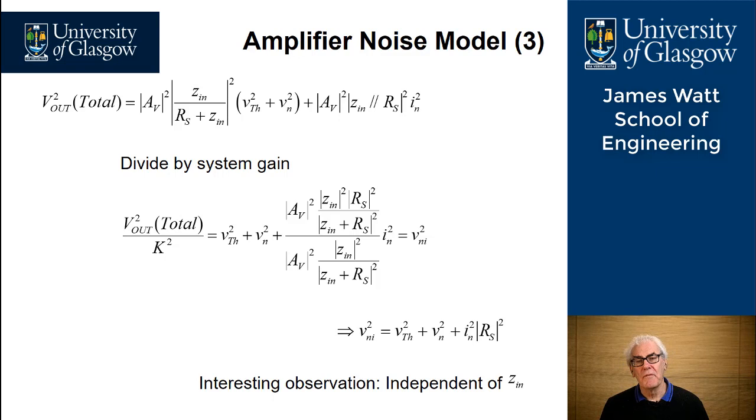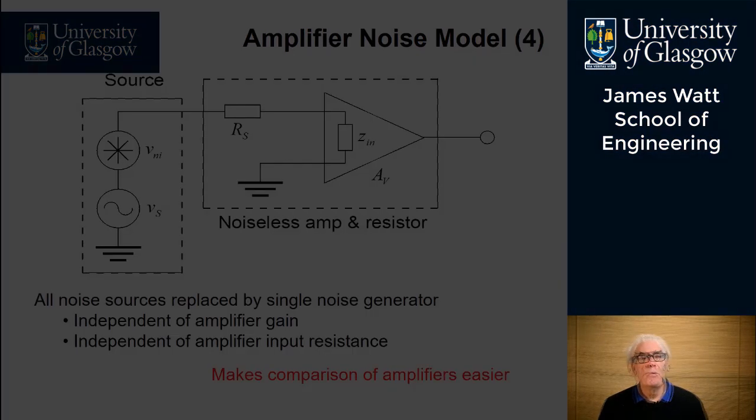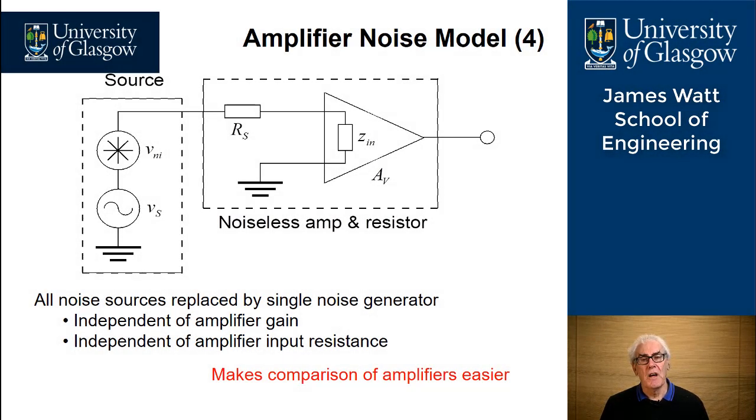And an interesting observation we can draw from this is that the actual input impedance of the amplifier is not important in this equation. It's actually only the source resistance that gives rise to the calculation of the total noise squared at the output of the amplifier.